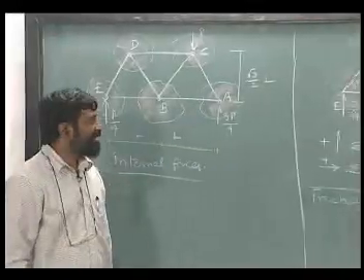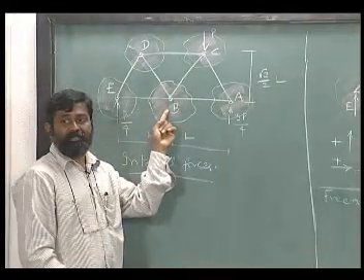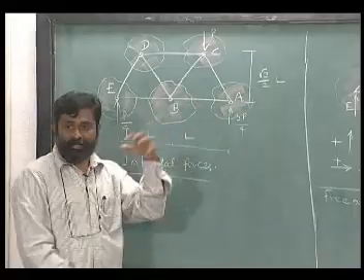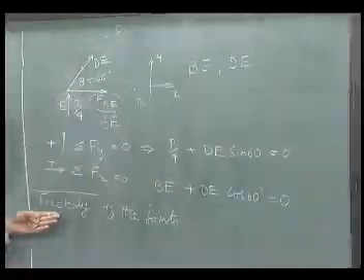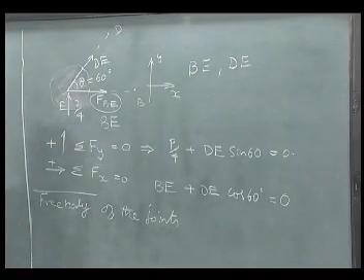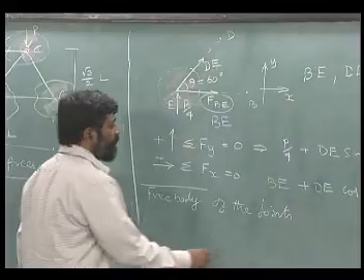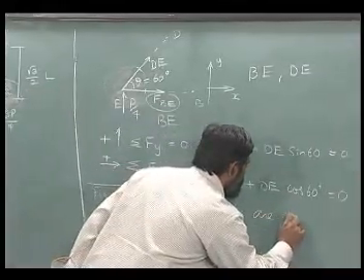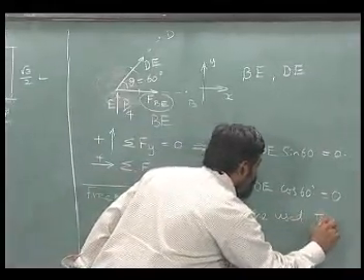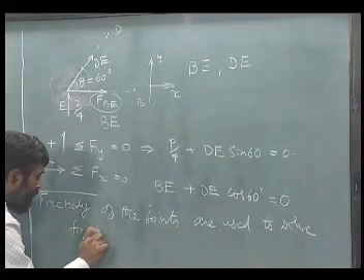What I have essentially done is I have engulfed, so that I have each of these joints separated. So, I can have free bodies associated with each of these joints. So, I am just going to call those free bodies of the joints, used to solve for member forces.